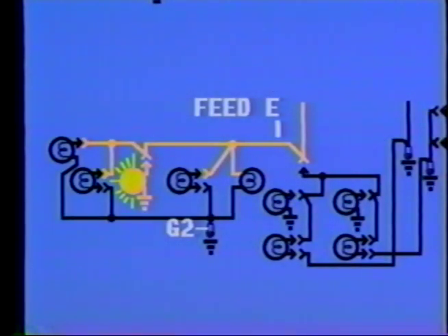The last two responses could cause our lights out symptom. An open at ground circuit G2 removes the common ground for all the suspect lights. In one shot, this would cause problems in the tail lights and the rear side markers, but not the license light. This is more probable than all four bulbs blowing out at the same time, as stated in response D. So response C, open at ground 2, is the most likely cause of our symptom.